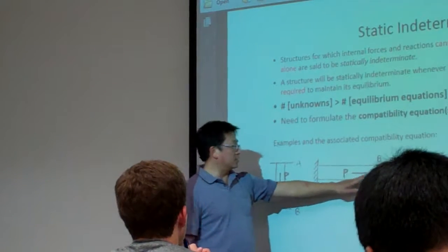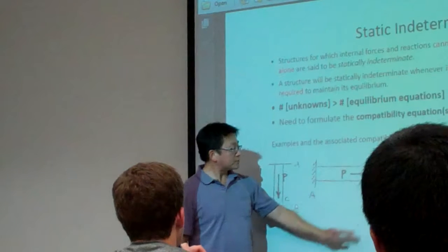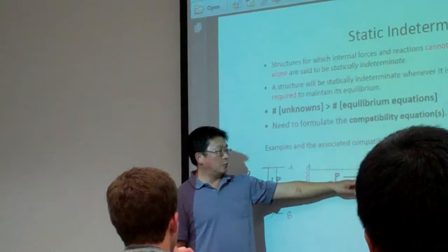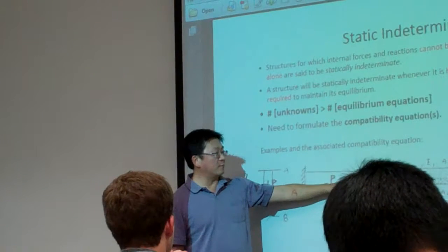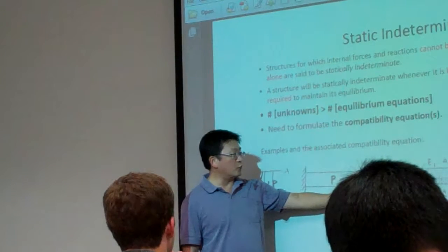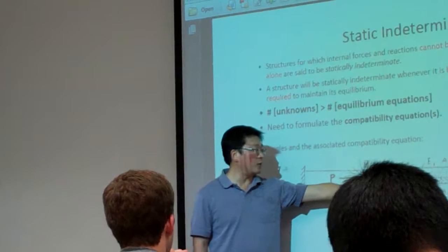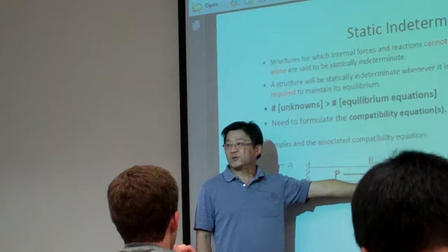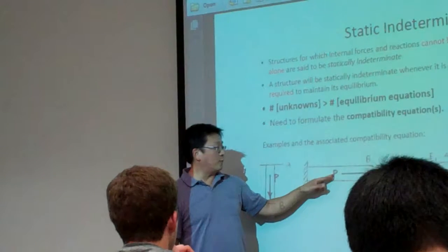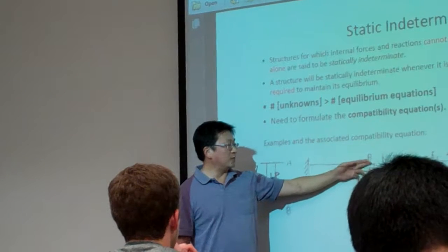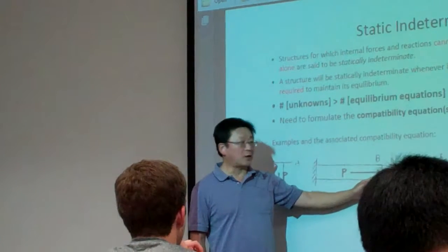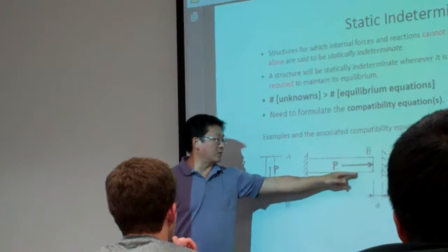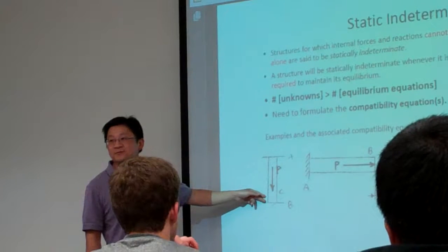The other one is this example, which has a gap. If the force is small enough, then the deformation at this end wouldn't touch the wall. So the problem would be equivalent to our traditional determinate problems. However, if the force is big enough to push this end to not only touch but push the wall, then once the gap is closed, the problem will become like this.